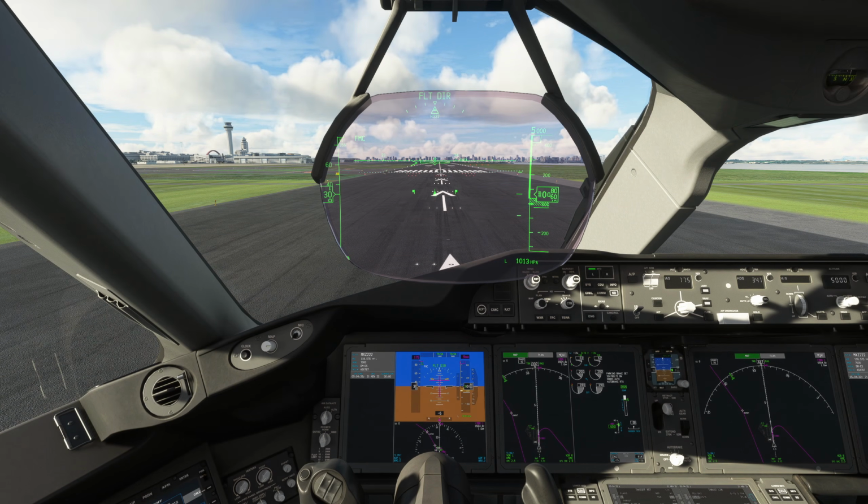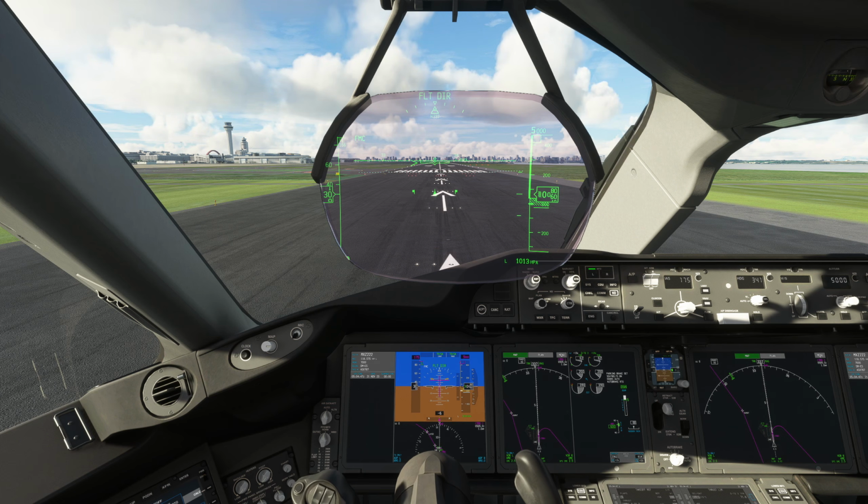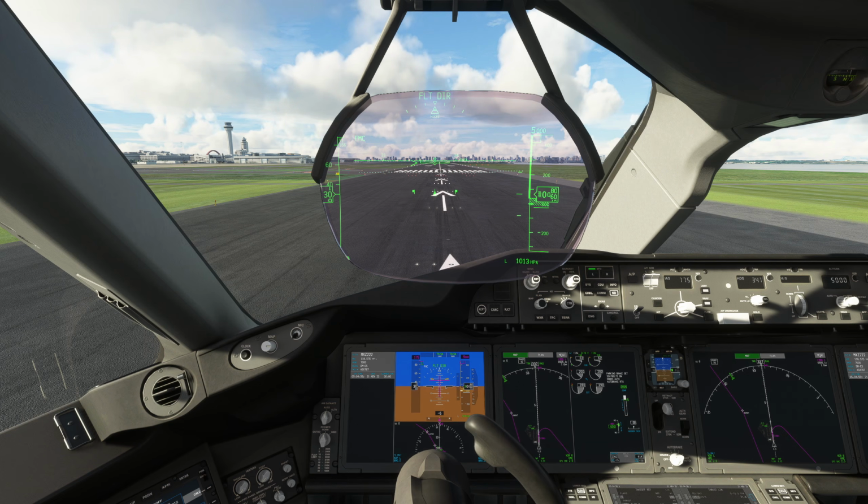We didn't do this on the Airbus. It was not something you were supposed to do unless it really needed it, and even then it almost never did. But on the 787, we do keep the wings level like that. Now that's in a stronger sort of crosswind scenario. In a light crosswind or a few knots, you're really not going to need much at all, if any. So in 5 knots or something, you're not even going to need to do it probably. But yeah, if you notice the airplane is starting to bank one direction, you just need to put in enough aileron to keep it wings level, and that's it.